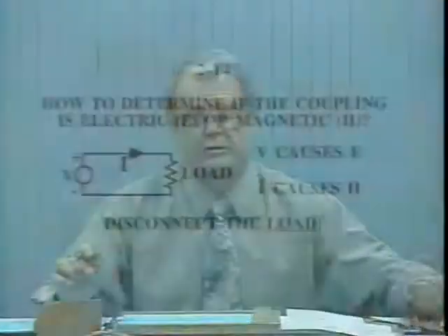It was the current producing the magnetic field around the cabling, right? The voltage you see is still present. Between the wires inside this cable, the voltage exists, the electric field is still there. So if it were an electric field coupling problem, it would still be present. But the fact that I've eliminated the current and that eliminated the problem says it was a magnetic field problem. So that's a technique we could use to diagnose the situation.